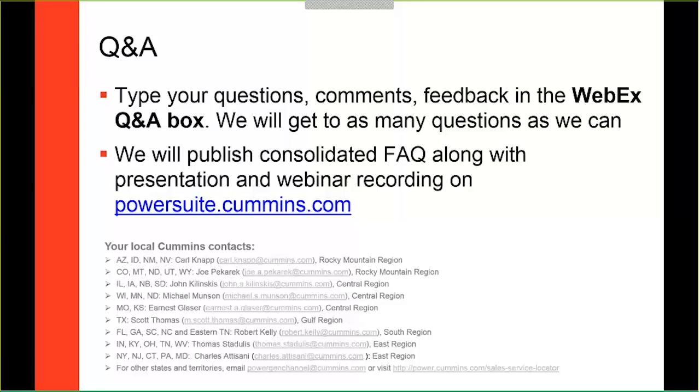There have been some things that have changed in regards to, say, Tier 4 final. I talked about it very briefly, but for stationary non-emergency and non-road compression ignition, everything today is Tier 4 certified. One of the things we did see recently was the addition of inducement mitigation in order to bypass inducement for emergency applications. However, as far as an overall relief or change in regulation, no, I don't see that on the horizon.